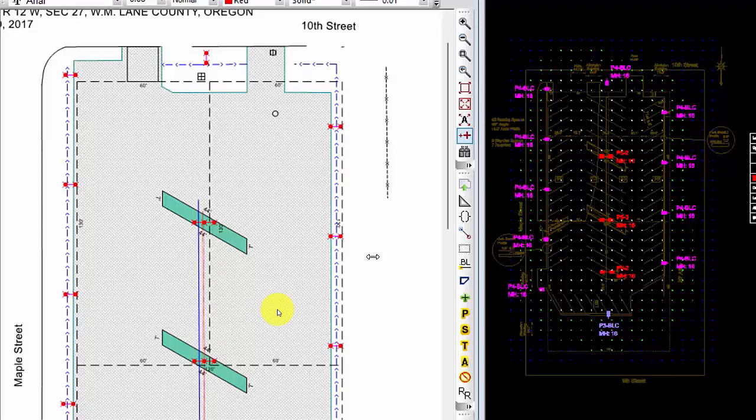And so I sent the property boundary, the paving edge, I had the striping turned on in here, to Hubble Lighting, and said, this is what I need for dark sky compliance, minimum lumens, that sort of thing, per the city requirements. And my project is in state plane. So I sent them a CAD file with state plane coordinates.